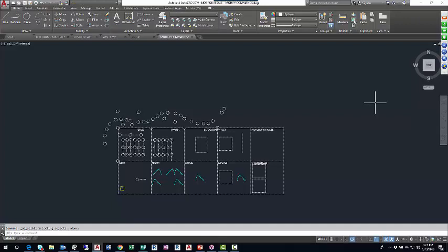there we go. I must have missed it the first time. Click select all, everything gets selected. On the command line it says AI_SELALL. It's something like AutoCAD interface select all. A lot of times these command line prompts, the command line information that follows the pressing of one of these buttons, might look like nonsense, but it really is just AutoCAD's shorthand for the macro that issues that command or what have you.